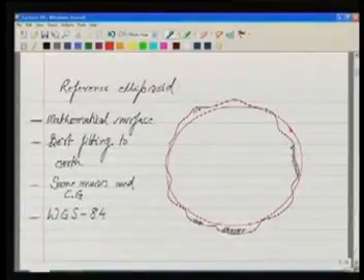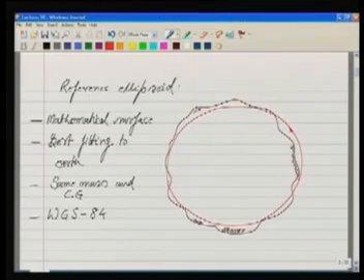Unlike in surveying, because in the case of surveying and engineering surveying, so far we just discussed somewhere a geodetic survey, but mostly in engineering surveys we can consider our coordinate system to be a local coordinate system, unless the project is very large, and in that local coordinate system we can carry out all our measurements, all our setting out. Over here in the case of the GPS, for the coordinate system we would like to define a reference ellipsoid.